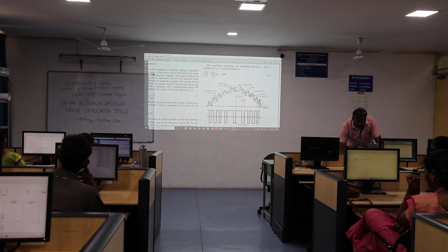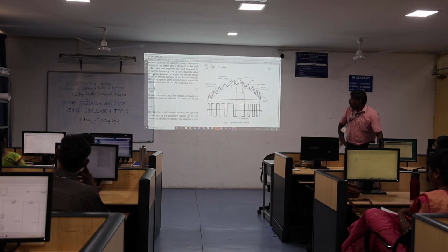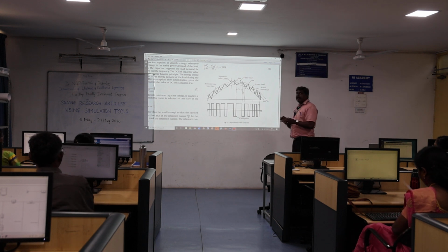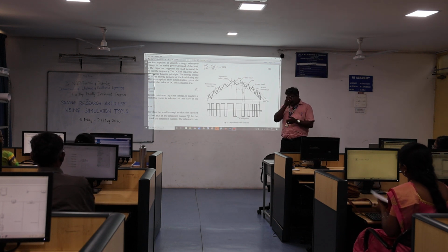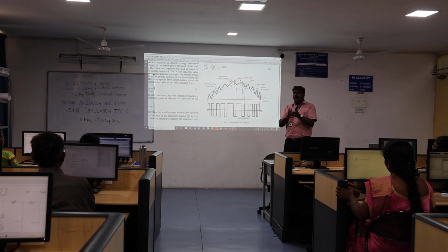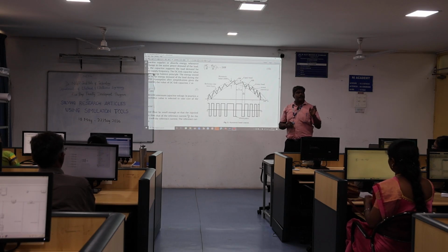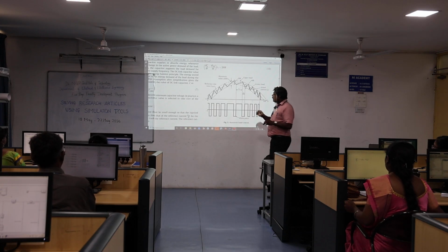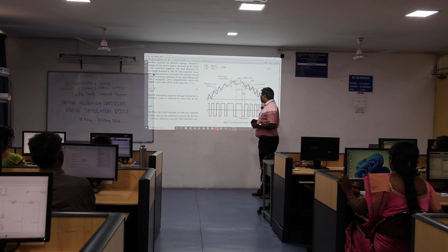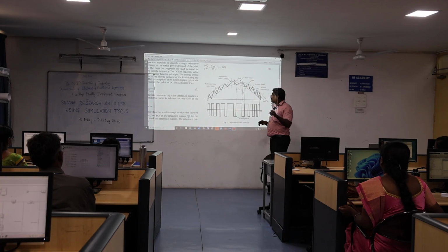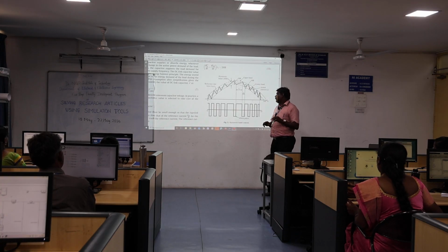So this is the hysteresis current controller. In the previous block, you know very well about the PI controller transfer function. The output of the PI controller is some K value, multiplied by sine omega t taken from the supply side, generating our reference current. In MATLAB, we use the relay block.